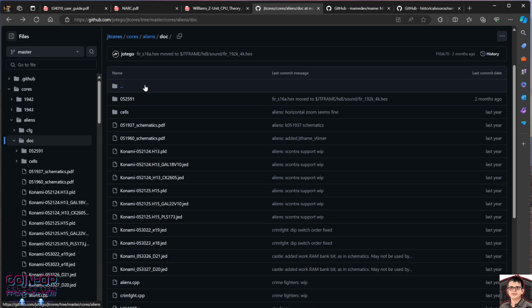Plus, your CPU access is basically governed by the operating system, right? So you can run it as fast or slow as you want to. Depending on how powerful your computer and CPU is, the emulator might work differently. But in the FPGA world, that experience will be the same across all the units that have that FPGA in it. Now, there may be cases where you have different dev boards and you're porting it to different platforms and all that stuff. But generally speaking, as long as the FPGA builds, and it's a comparable FPGA with similar logical elements, similar cells, and all that stuff, it should technically work the same.